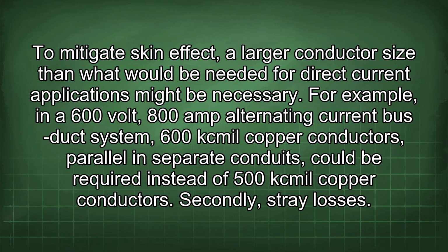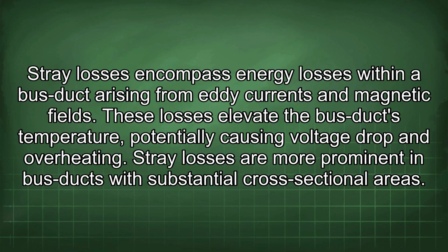Secondly, stray losses. Stray losses encompass energy losses within a bus duct arising from eddy currents and magnetic fields. These losses elevate the bus duct's temperature, potentially causing voltage drop and overheating. Stray losses are more prominent in bus ducts with substantial cross-sectional areas.